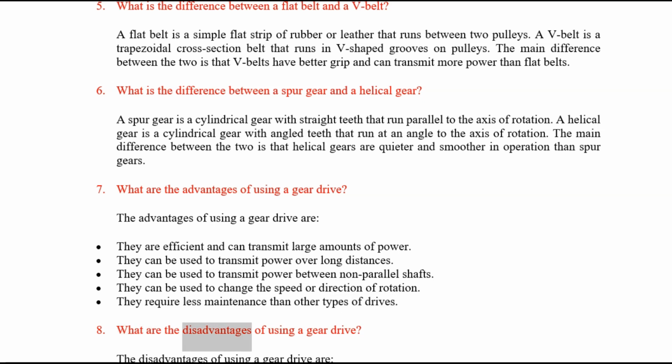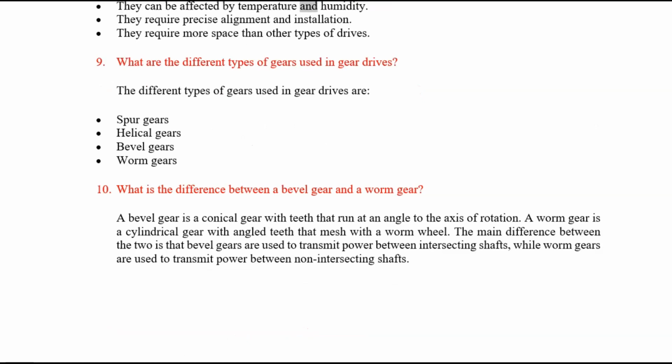What are the disadvantages of using a gear drive? The disadvantages of using a gear drive are: they can be noisy in operation. They can be affected by temperature and humidity. They require precise alignment and installation. They require more space than other types of drives.